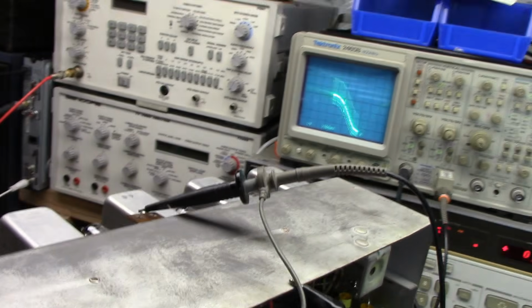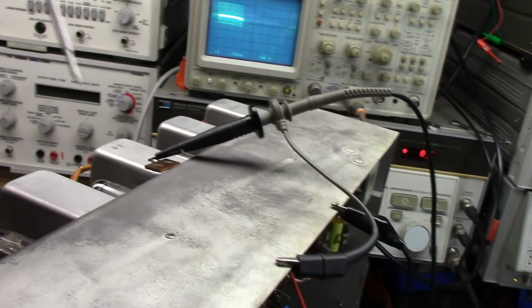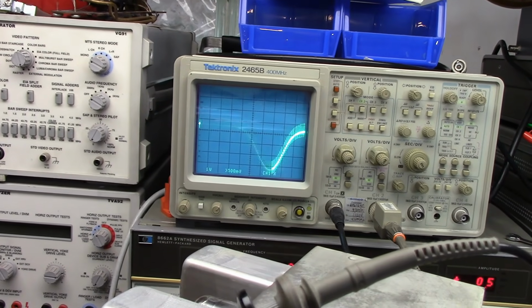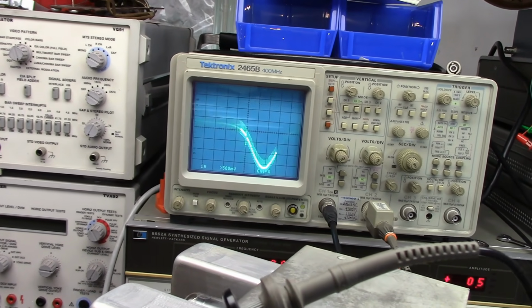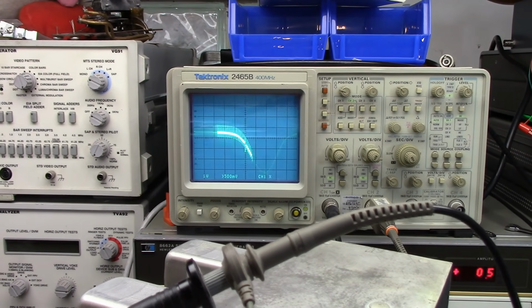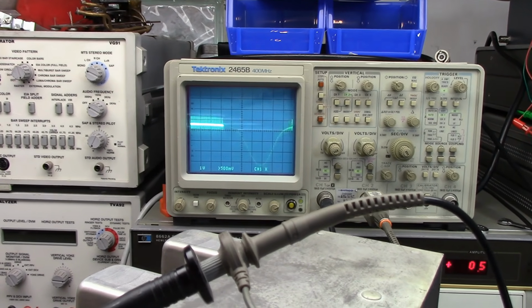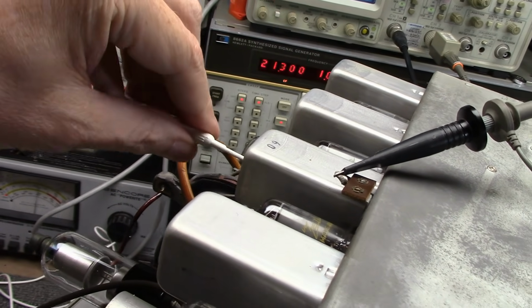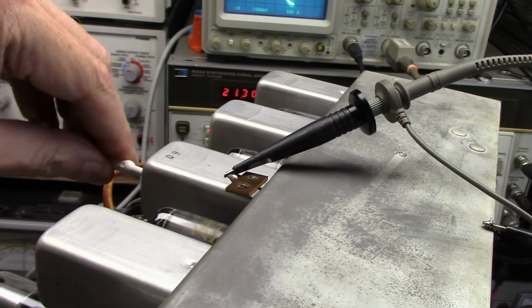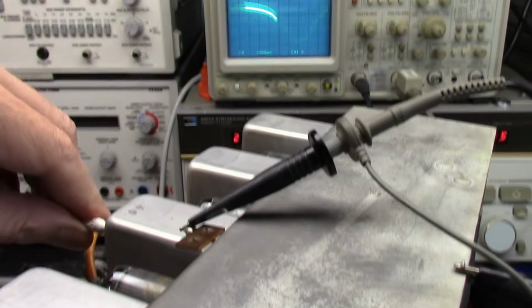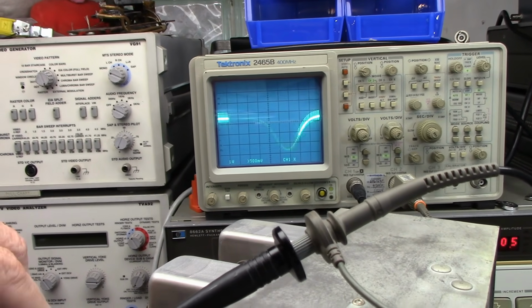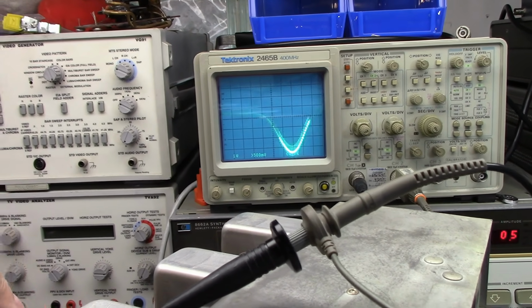Alrighty, so again, with our hex tool, now we're doing this can. We want to move that over to the left. And, oh, my luck just ran out a bit. The good old dreaded frozen core. It doesn't want to move, at least the top one doesn't. Let's see about the bottom one. Okay, the bottom one I can move. I may go up and down, but I need to make it move over to the left. I really got to move that top slug.